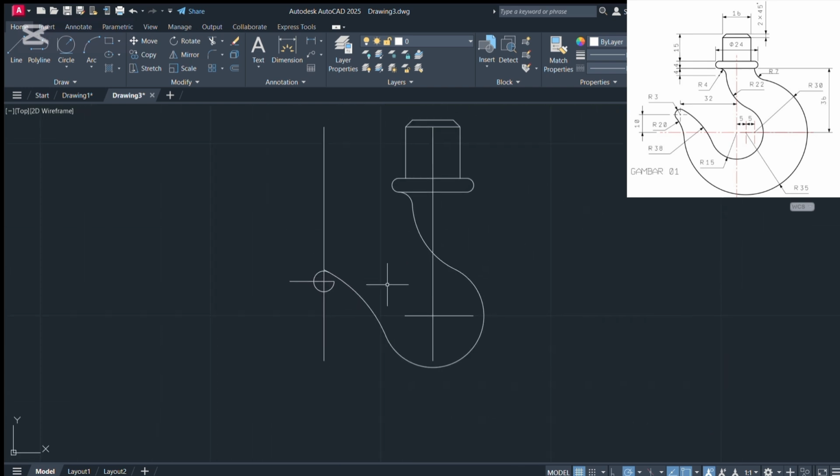Alright, so next up, what we're going to notice is that on the right side, we have got another center that is at a distance of 5, and again another center that's at a distance of 5. So the first one we're going to deal with will be the first distance at 5. So we're going to copy the center line that we had done at first. Then move your mouse to the right, then click 5 on your numbers, then click enter.